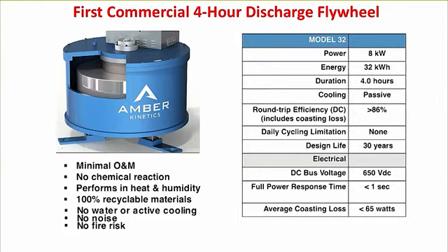So one has energy in the rotational inertia of the rotor, and then power in the motor generator and the power electronics. And in principle, there's a lot of degrees of freedom in design, and the 4-hour ratio is largely a stab at where the market is, partly driven by the California market.